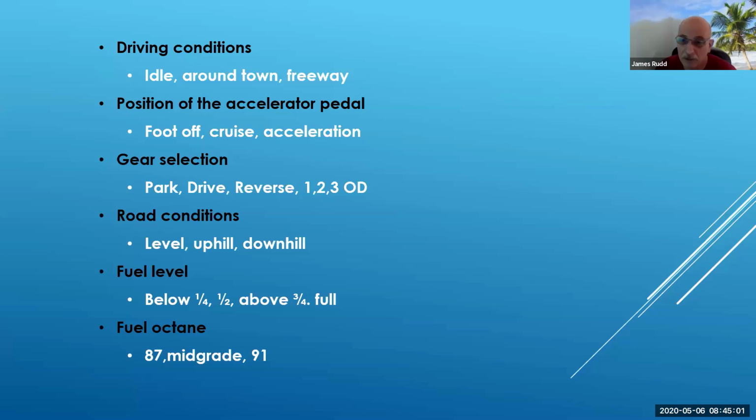Some of the Hondas actually had a switch to let it know it was in gear or not, and part of that had to do with the clutch switch. If you hit that and it didn't activate correctly, it would not take it out of base programming, and it wouldn't go into more of a performance mode. So you would have some hesitations and some kind of non-performance issues like that too.